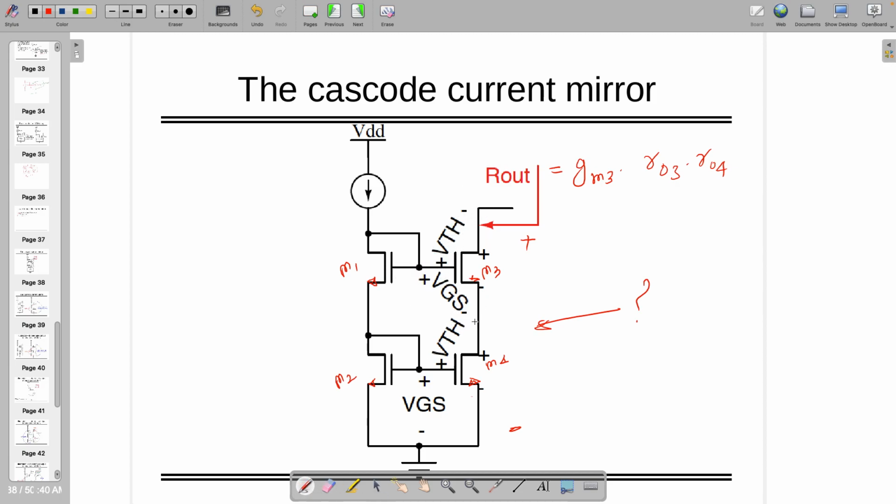So here, if it is only this transistor, if you remember, last time we kept it here VDS. VDS is nothing but VGS minus VTH. So we kept VGS over here, plus and minus, and VTH is minus, so reverse polarity. Same thing I followed over here. In that case, what is the potential looking from here to here?